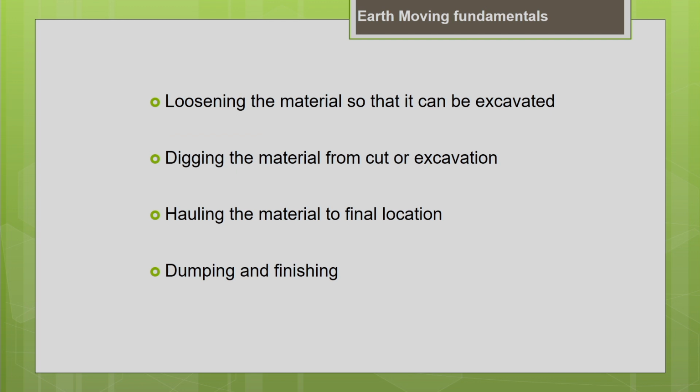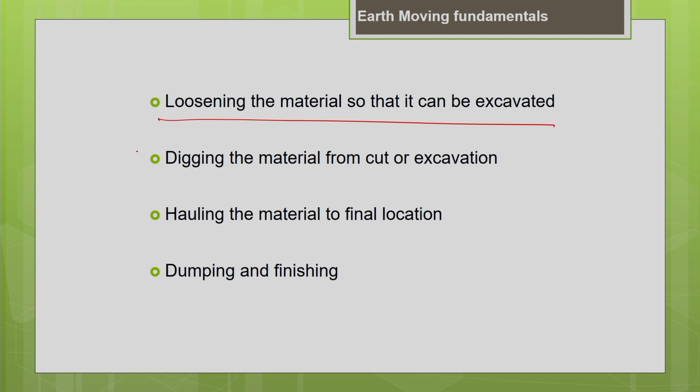To start with, we first have to loosen the material which we are trying to move, so that it can be excavated. If we loosen it before digging, it will be easier to dig, and it will enhance the productivity of the job. So, the first step is to loosen the material. You can use a tractor with a ripper to loosen the earth, followed by digging the material from the cut or the excavation.